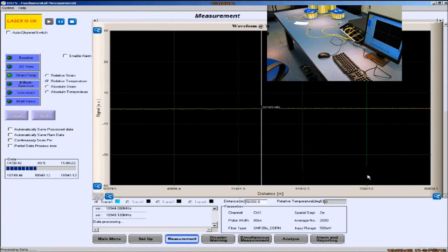So a relatively small change in the length, from 120 kilometers to 100 kilometers, allowed us to tighten the pulse width from 200 nanoseconds to 80 nanoseconds in order to generate a good signal that the Brillouin sensor can measure. So this shows just how the relationships work between fiber length and sensing resolution.